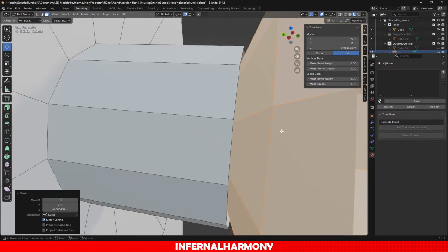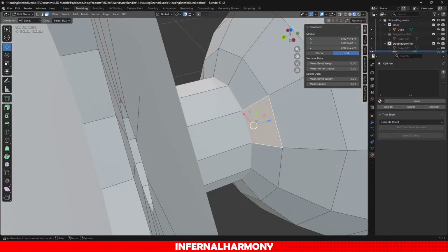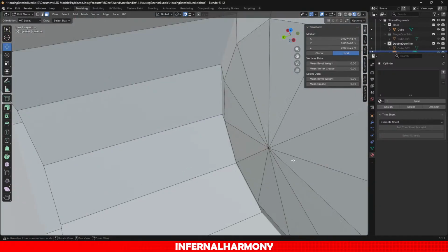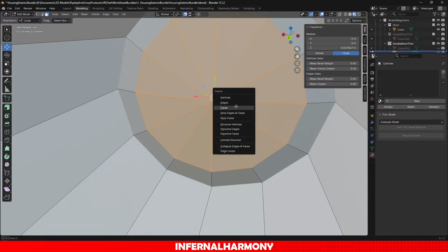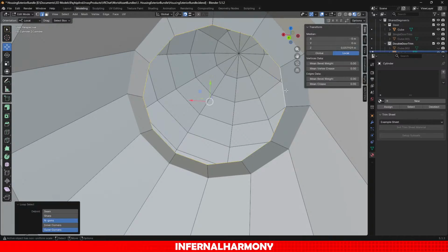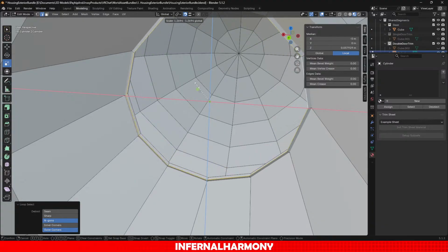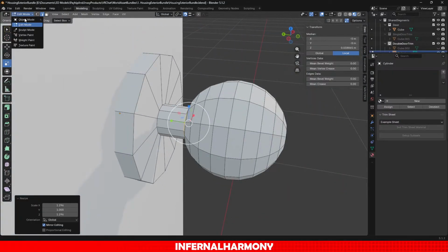And I'd like to try and get this as close to this as possible. Oop, on the y-axis. Then what I can do is delete those back faces here, and because of the way I've got it designed or set up, select these faces here, delete faces, I can then do this, vertex merge nearest, and start scaling it outwards. There we are. That does it. Simple handle.